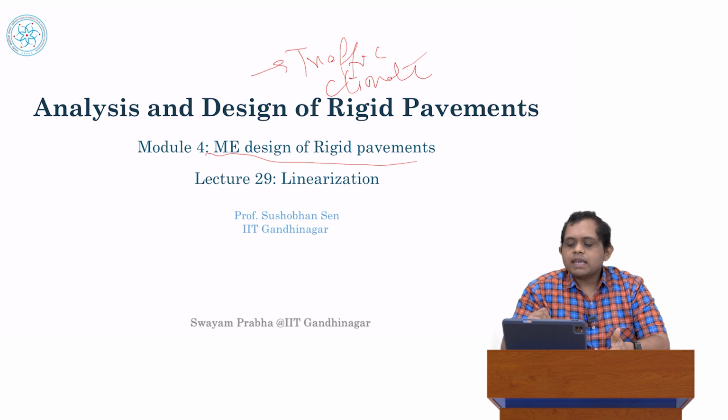and that basically was adequate for us in terms of characterizing traffic. In the analysis of rigid pavements in mechanistic empirical principles, however, that's significantly more complicated. We saw that we have basically four types of axles. We have single axles, tandem axles, tridem axles, and quad axles. So we need to know firstly what our axle configuration is. Then we also have to know what our axle load is. What is the load which is carried by each axle, which by the way may not be evenly distributed across the vehicle. We talked about that previously.